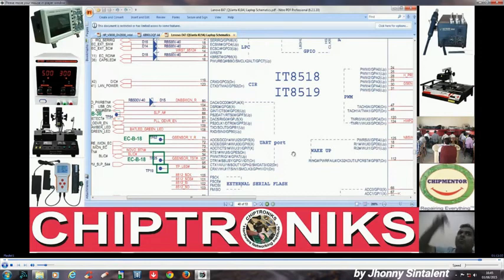That is, if we want to read the information from the 8048 microcontroller present inside the desktop keyboard, the CPU has to use the address 60H, right? Similarly, if the processor has to read the information from the 8042 keyboard controller present inside this IO controller, then it has to use the address 64H.